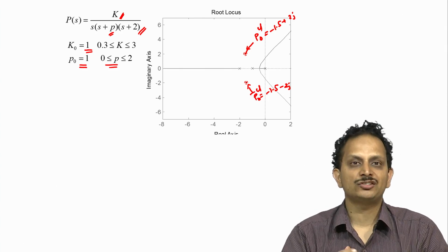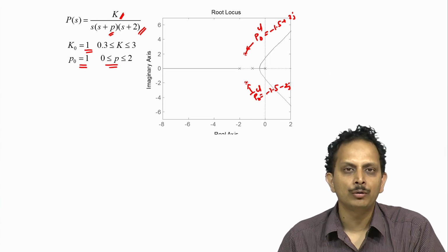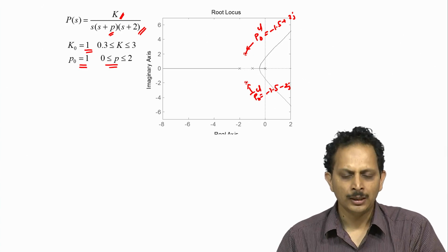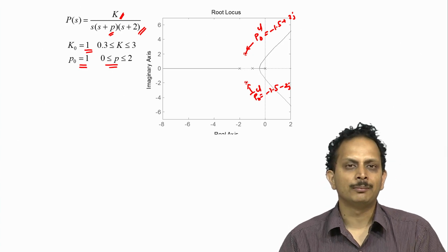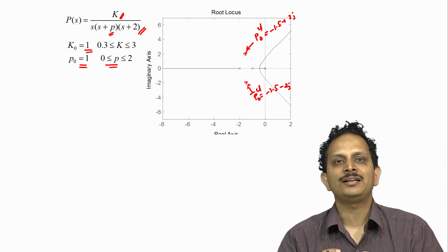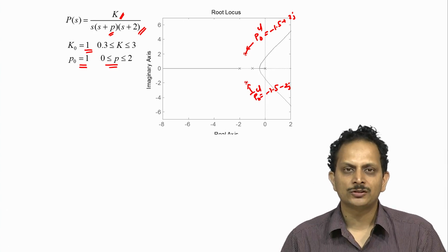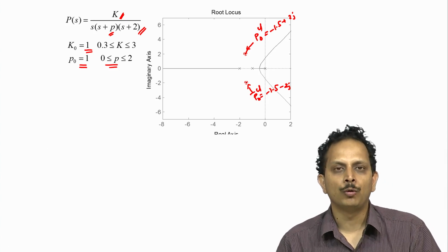Now we had to restrict the variation of the closed loop pole to within such a small area about its nominal position, primarily because the equations that we wrote when we performed the design using root locus could be simplified only when the permitted variation was much smaller than the typical distances between the other open loop poles